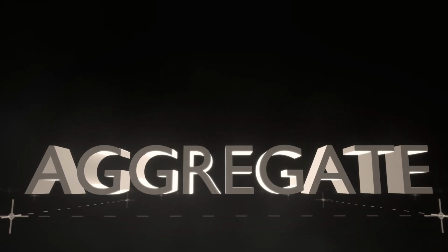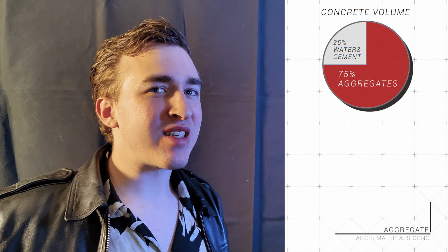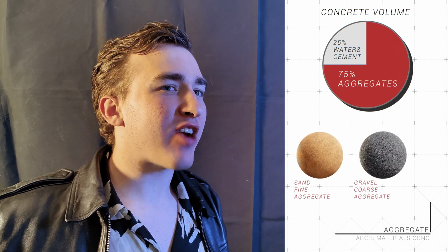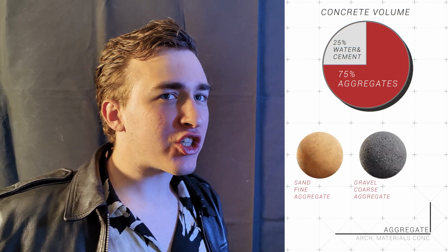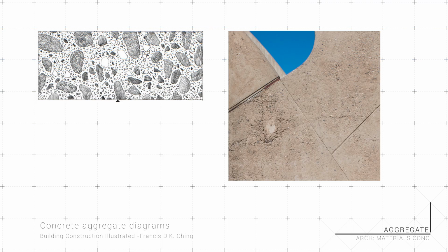Yet, cement and water aren't even the majority of concrete's volume. That goes to aggregates. Close to 3/4 of concrete volume is made up of fine aggregates like sand and coarse aggregates like gravel. The liquid cement mixture holds together all these small rocks as a liquid stone. It works like this. Coarse gravel pebbles are held together by the cement mix. The compression of all the gravel bits pressed together gives concrete its strength to support large frame systems.